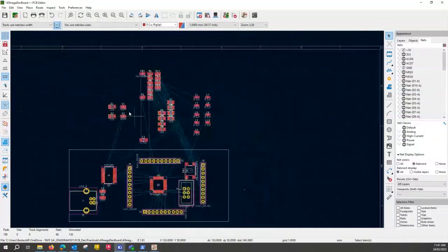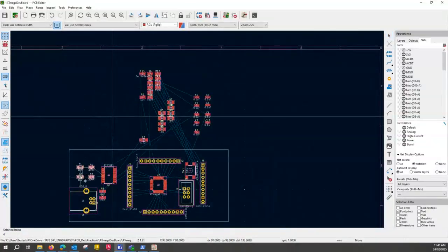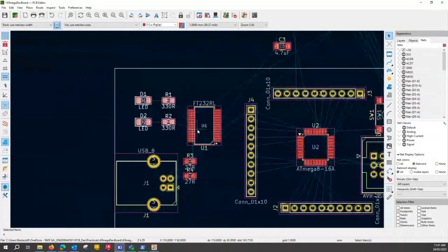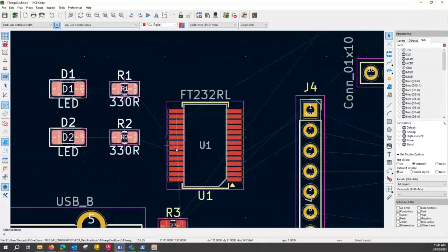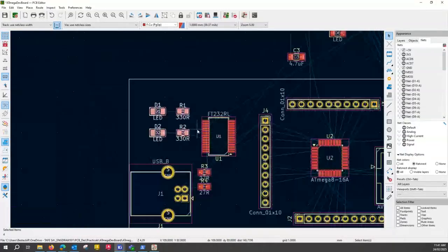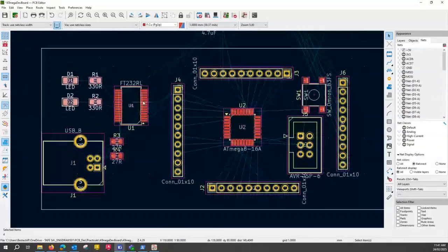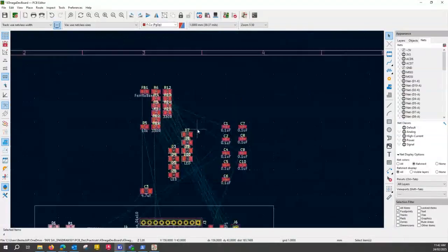What I'll do is I'll position them, because this is my RX TX indication. I'll position them here somewhere. Now, obviously, I can reposition them later. You can see that they connect to those 2 pins, so this is a good location for them. Also, if you look at the actual board, you're connecting your USB through here, and then you're monitoring your communication, and those 2 LEDs are flashing, telling you which way the communication is going. So it's reasonably good position for them, I guess. What else do we have there?